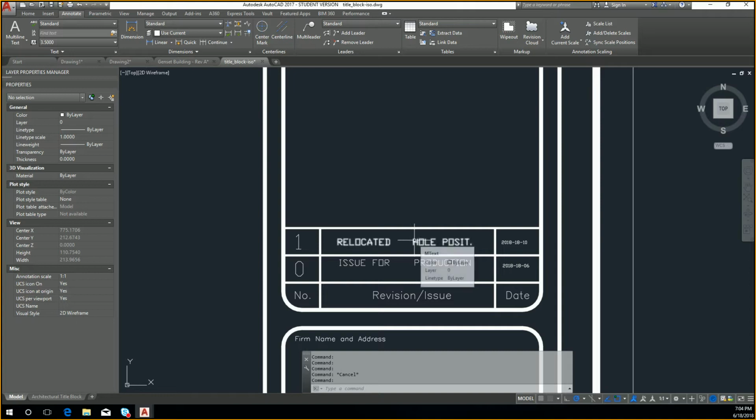So this is sort of touching into something beyond AutoCAD altogether, but depending on how you track your revisions, there's also things such as engineering change notices that are actually full documents that document all your changes. Because again, this all comes down to cost of services. It might sound simple. I need you to modify this little plate because they wanted rounded corners. What if down the road someone had already used that table and expected sharp cornered edges because they were going to mount something to it?